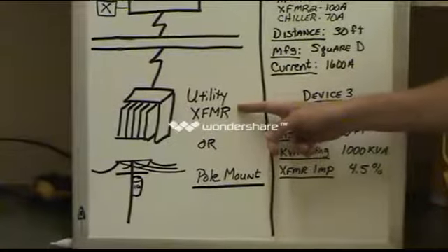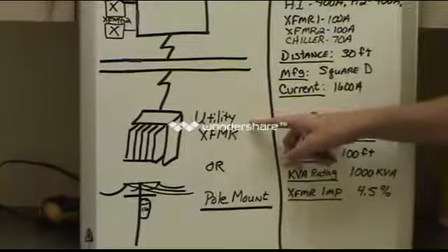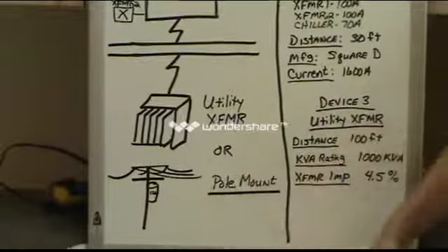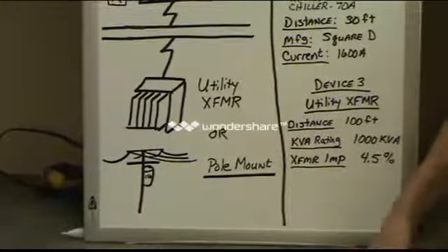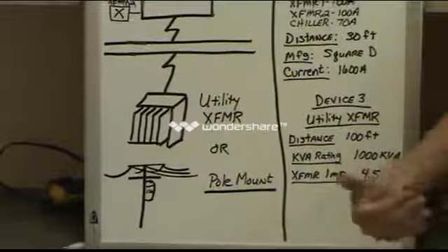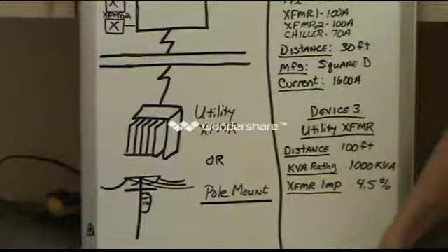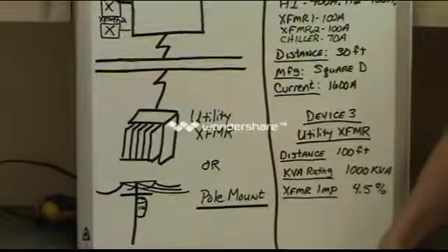Every single clinic or small facility is going to have a transformer either mounted on the ground or on the pole. So finding this information and telling me the loads is going to tell us a lot. It's going to give us a story about the site and how well that equipment is going to be running.